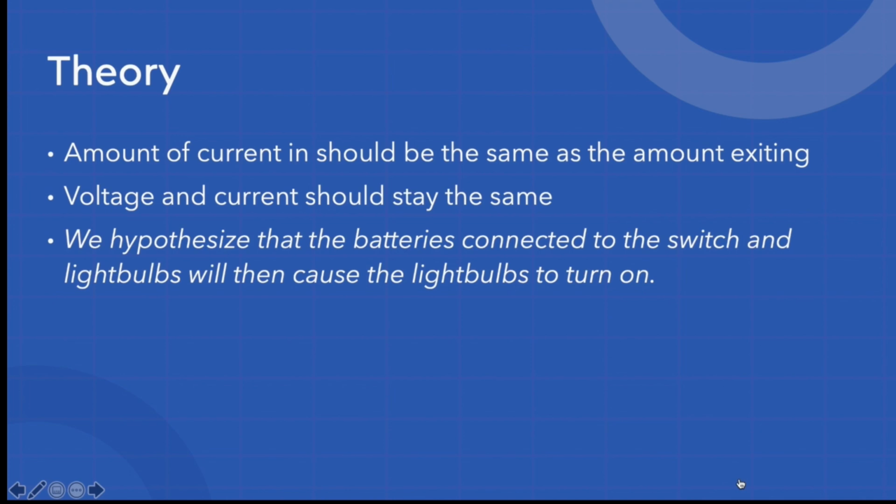The loop rule, also called Kirchhoff's voltage law, deals with voltages around a closed loop. A closed loop is any path through circuit elements where it returns to where it started without passing through any elements more than once. It states that the sum of the voltage rises because of the battery around a closed loop is equal to the sum of the voltage drops caused by the resistors around a closed loop. This is due to the conservation of energy.